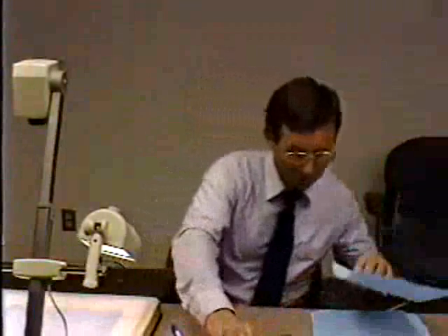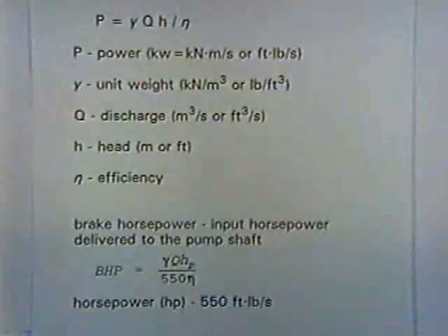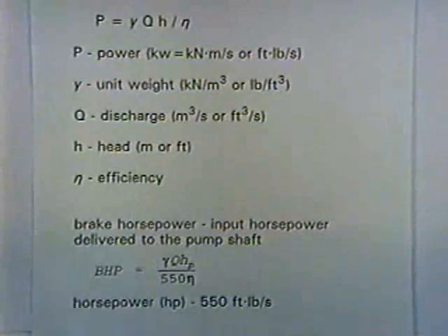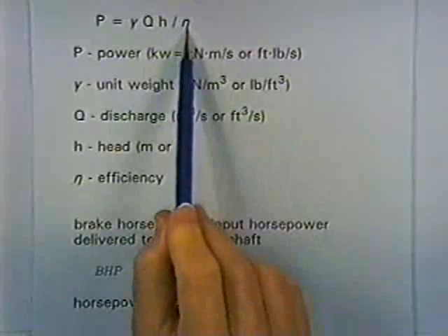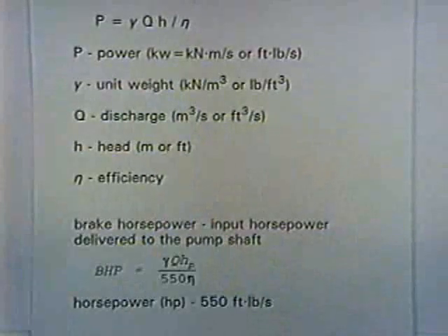And continuing with this same train of thought, actually in the power equation, when you're converting between energy, with a pump, we're converting electrical energy to hydraulic energy. Of course, we could also be talking about a turbine where we're converting hydraulic energy to electrical energy, but there's always some loss of energy. There's never 100% efficiency. And so we'll add in the efficiency, and the efficiency is the ratio of the electrical energy going in to the hydraulic energy coming out. So it's a number less than 1.